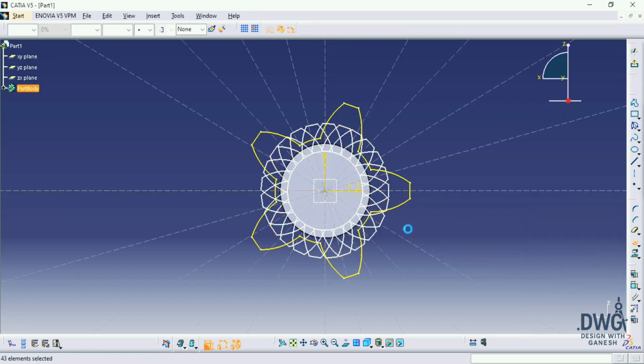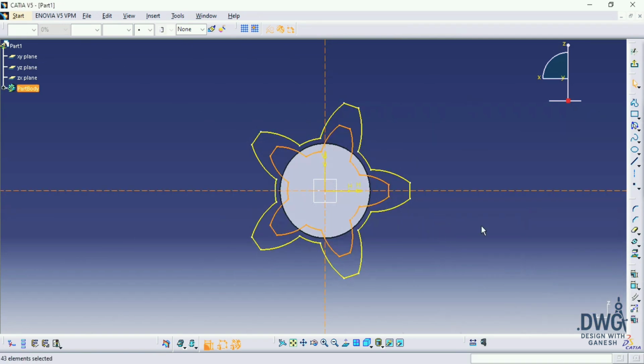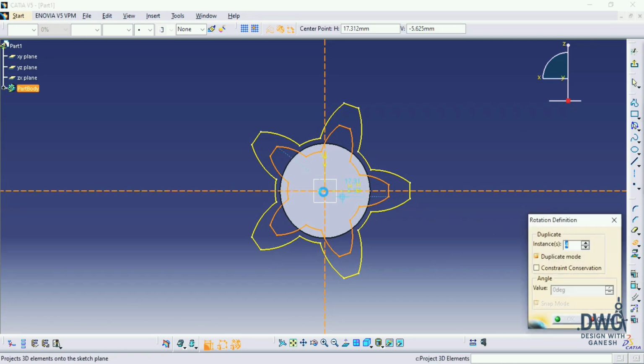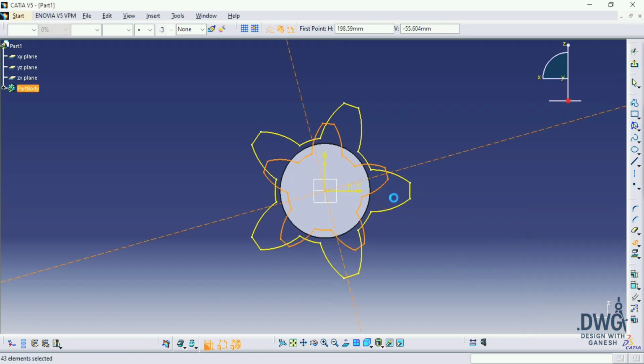You have to rotate. So control Z. What a mistake that I have done is, this way the entities are selected, this way the center point only, and take this one, this way only 15 degrees. That's it. Now select this one, make it a construction. Click on exit.